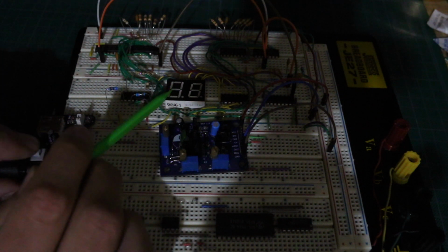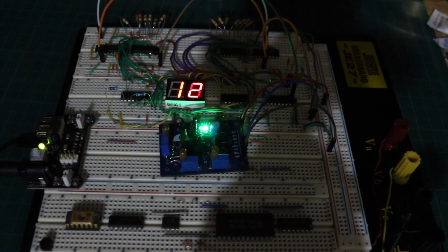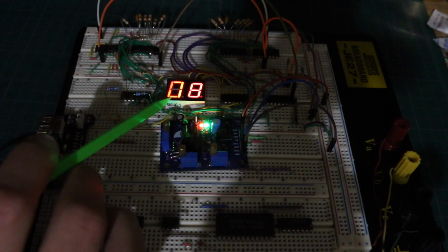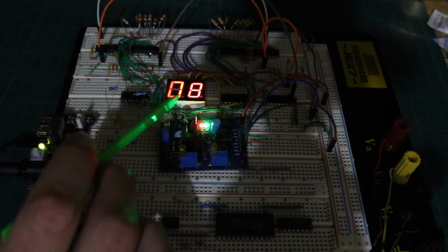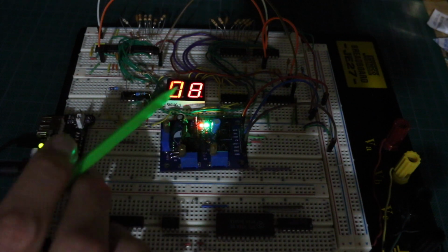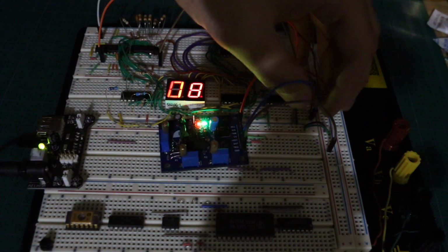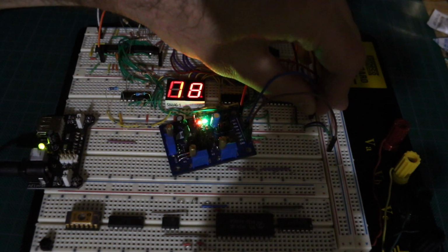So let's power on. We're at 0, and it should count to 19 and then go back to 0. And there it is. So now if I speed up the clock again, when it's going so fast that we can't see, it looks like all the digits are lit on the 1s, and it's going between 0 and 1 on the 10s. So when I pull the clock, it'll stop on a number between 0 and 19. 15. If I do it again, 9, do it again, 18, 7.